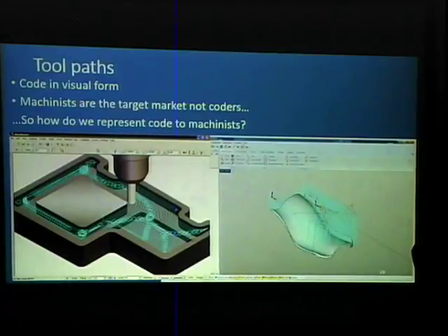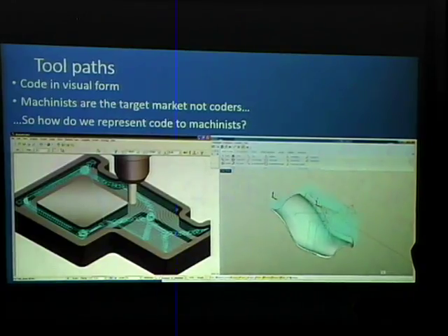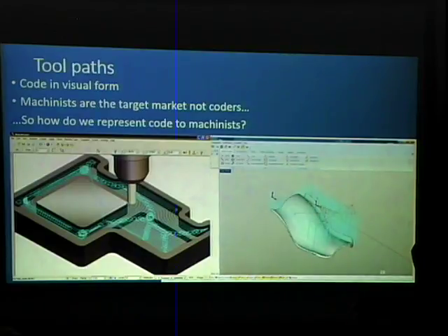The advantage of the CNC machine is, one, it can be more powerful because you've taken the operator and moved them away from the tool, and they can sit in a chair and watch it on a computer. That means we can put 40 or 50 horsepower into the machine where previously we might have put 2 or 3. It also means that they're more precise. Computers generally don't make mistakes. They make mistakes, but they're less likely to make a mistake than the human error component at the coding side or the human error component of running these things by hand.